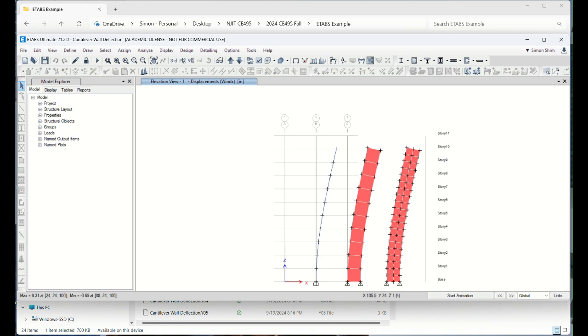But here, the finite element software using beam elements gives a model estimation of 9.31, a little bit of overestimate, right? 9.31 versus 9.23, what? 1% difference, 2% difference, 5% difference, right? How about 9.18? Oh, area elements somehow overestimate the stiffness relatively. You see the 9.18 versus 9.31. Our theoretical number is 9.23. You see the difference?